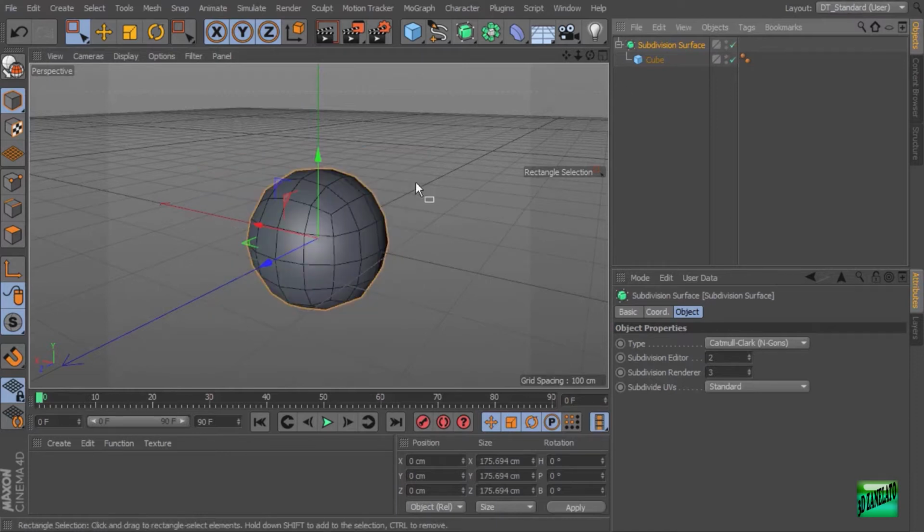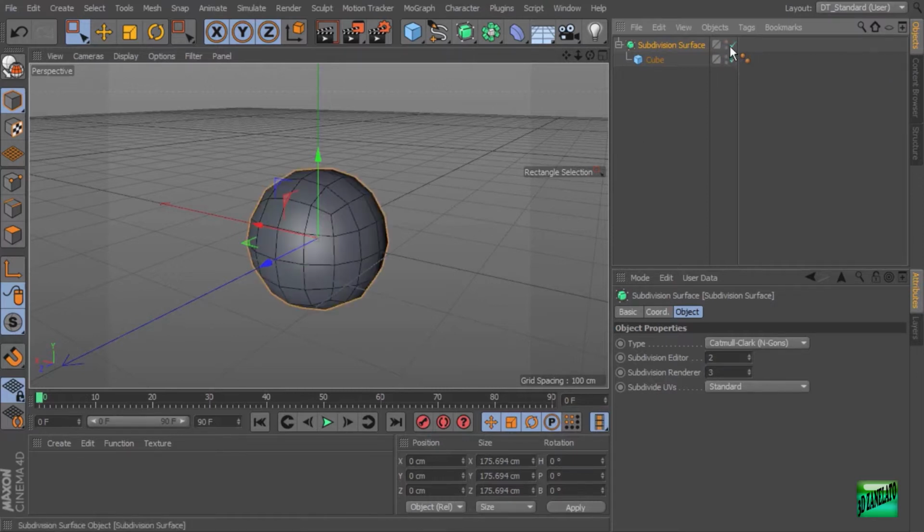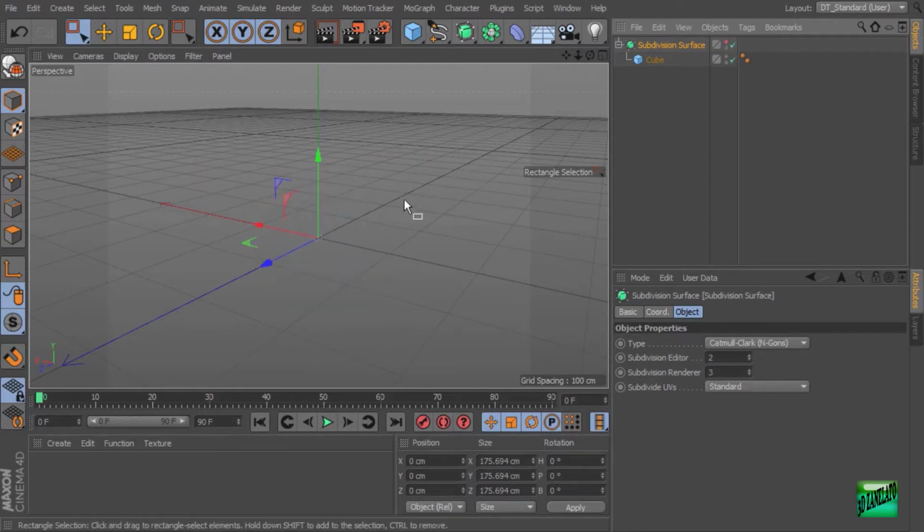Let's turn off the visibility of this and look at some splines. To do that, we can use these little street light kind of things here. So if I hit this one, it's going to turn it green, which means it's visible. If I click it again, it's going to turn it red, which means it's invisible. Click it again and it's default. So I'm just going to turn this off. Also, if you're at default and you want to go back the other way, you can, I think it's shift, and you can go back.